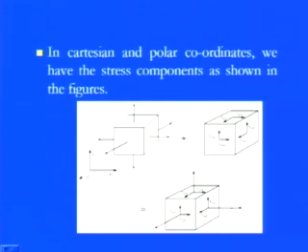So as we have seen, as well as the normal stress components there are the shear stress components, and if we want to combine those in these three domains, x, y and z, we can straightaway combine them. Now we have 6 components from the shear stress and 3 components from the normal stress, so in total we have 9 components. This is the real diagram in which we can see how these normal stresses as well as shear stresses are acting, and what the combination of these stresses is at a particular point in these 3 domains.